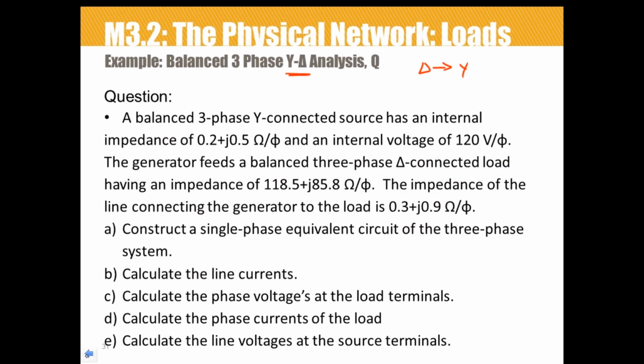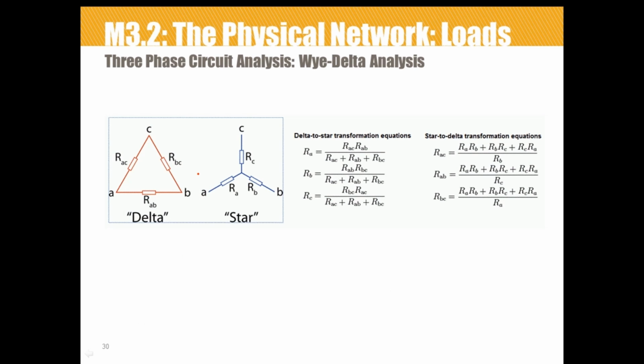So I'm going to back up for a second, and here's a comparison of the two loads, better drawn than I was able to draw it on the last one. What you'll notice is that in a Y equivalent, we have a phase voltage measured across the phase, and then we have a line voltage. Those are different. Sometimes this voltage is called line to line. In the delta, V phase is equal to V line to line. They're the same voltage.